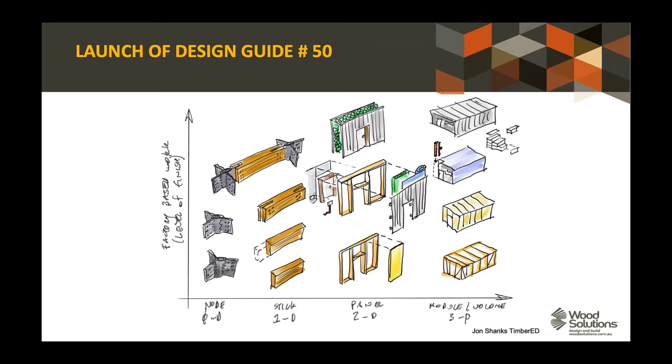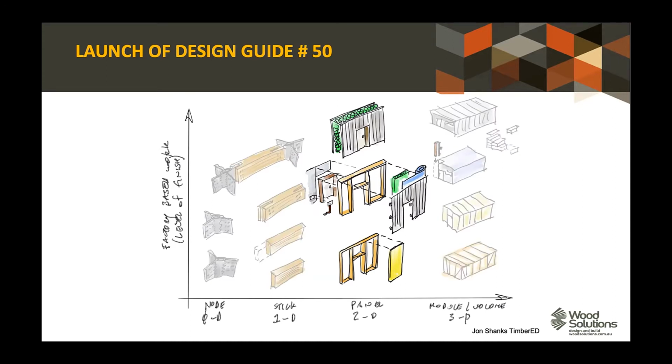Most commonly, what we're talking about in this mid-rise space, although there may be some volumetric construction and there may be some stick-built construction, what we're really talking about as the sweet spot is typically around panelized prefabrication. That middle zone, those sort of 2D elements made up as either open frames, sheathed and insulated frames, and it really depends on a project-by-project basis what the most appropriate solution is. So typically, when we're talking about timber frame mid-rise, it comes with it an assumption that actually there will be panelized elements of prefabrication, wall frames, floor cassettes, and so on.